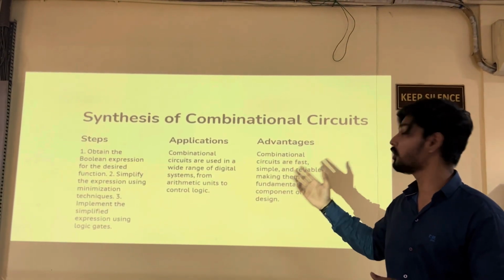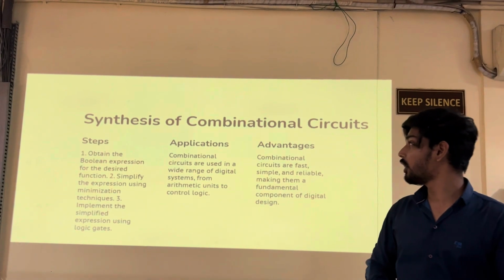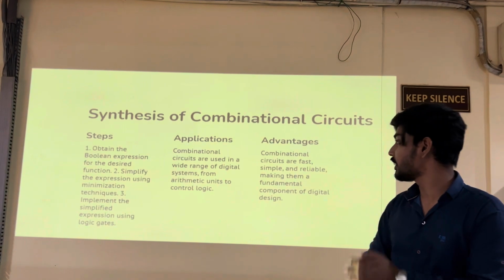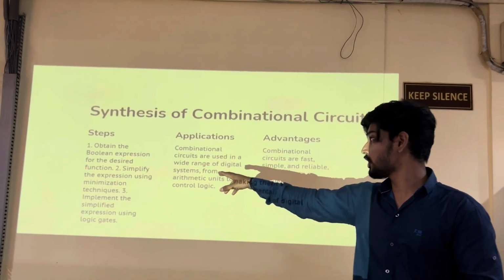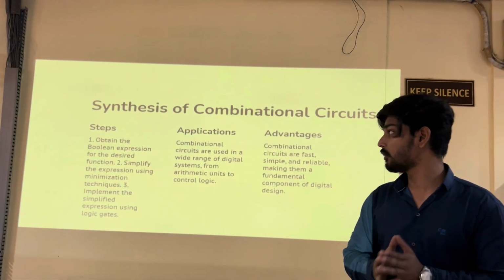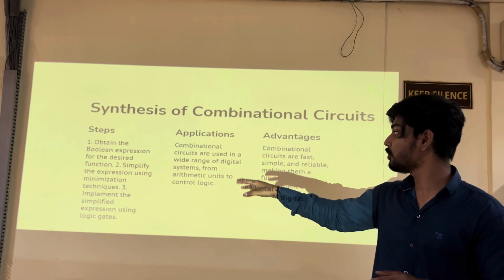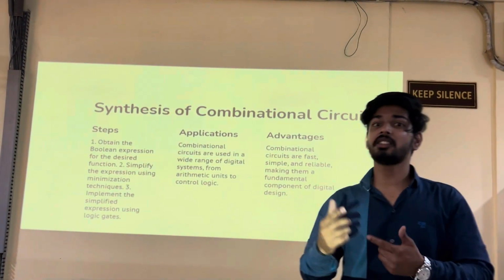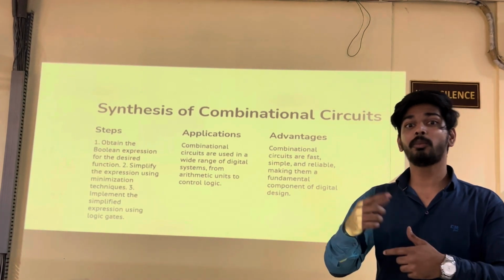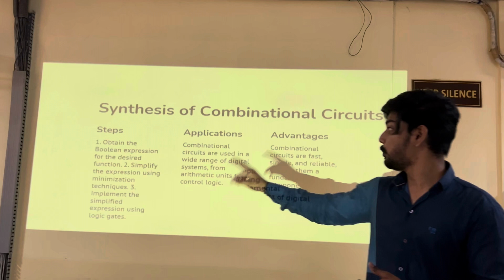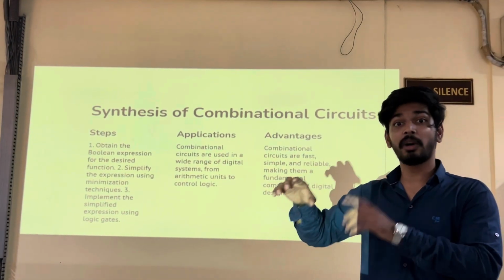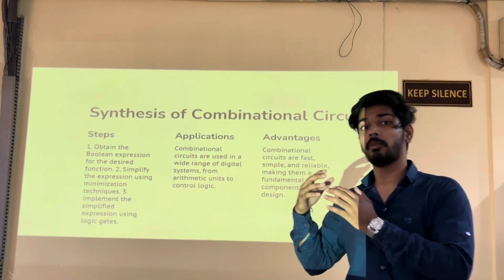This is synthesis of combinational circuits. We have different steps. The steps to follow in synthesis of combinational circuits are: first step, obtain the Boolean expression for the design function. Now the second step is to simplify the expression using minimization techniques, which we discussed in previous slides. In the third step, implement the simplified expression using logic gates. Now we will represent those minimized functions in the form of logic gates.